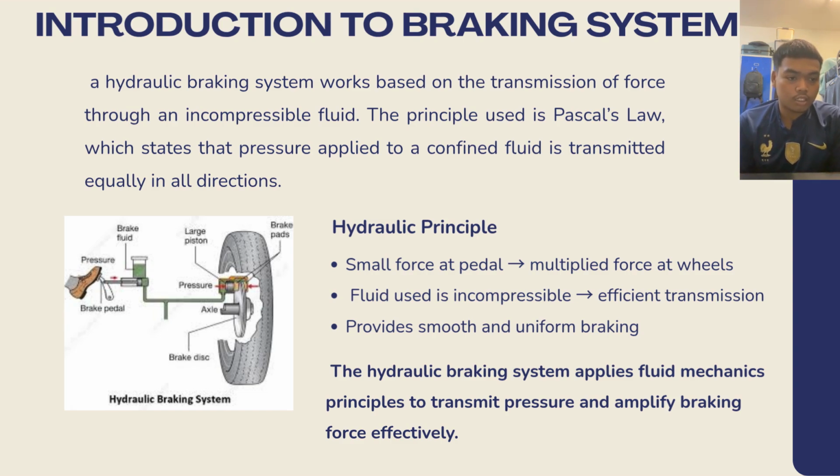Okay, for the introduction to braking system, we can look at this slide. Hydraulic braking system works based on the transmission of force through an incompressible fluid. The principle used is Pascal's law, which states that pressure applied to a confined fluid is transmitted equally in all directions. This is a hydraulic principle.